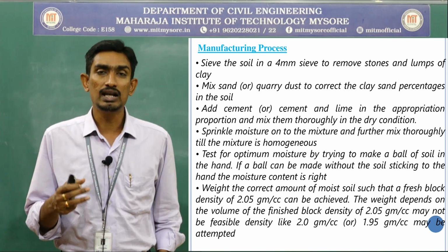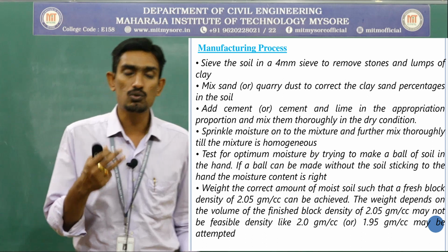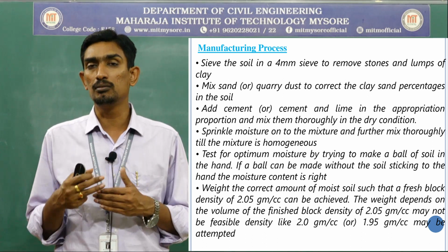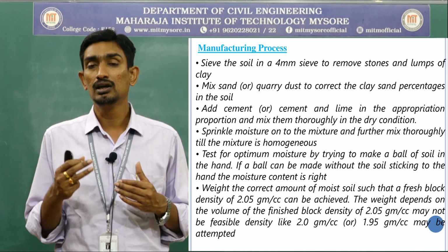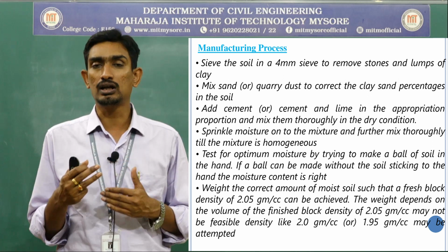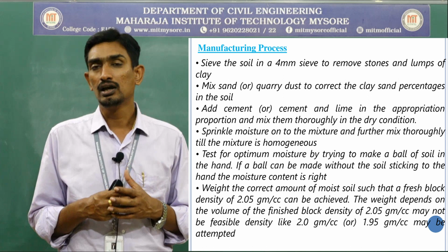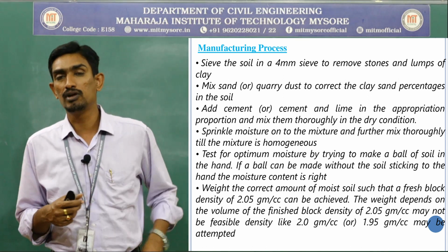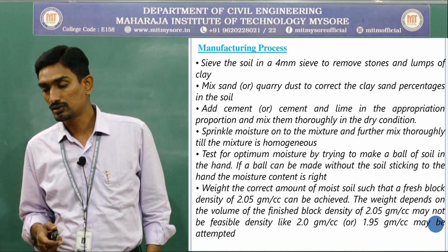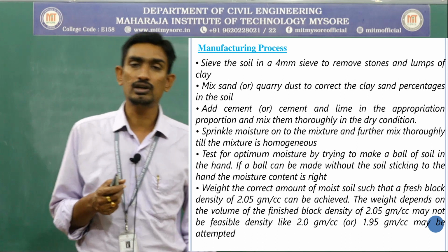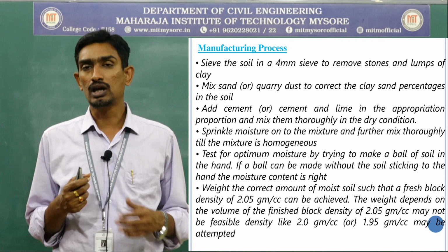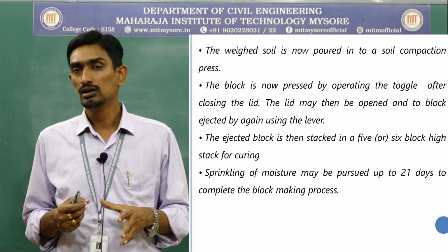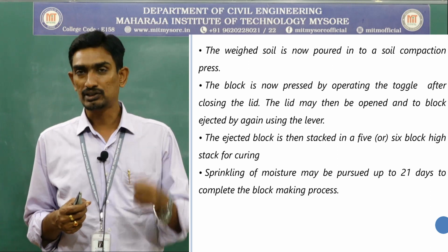So that's why while adding the spray, that is water, we need to be very careful. We need to keep adding a little bit and check for the OMC. If you add more water and it is very sticky, then I need to do a lot of corrections, so we need to be very cautious. Next, after mixing and attaining OMC, pour that material inside the mold and then press it.